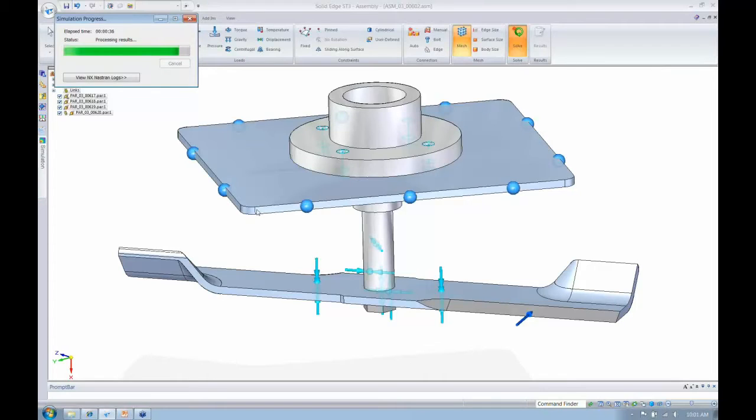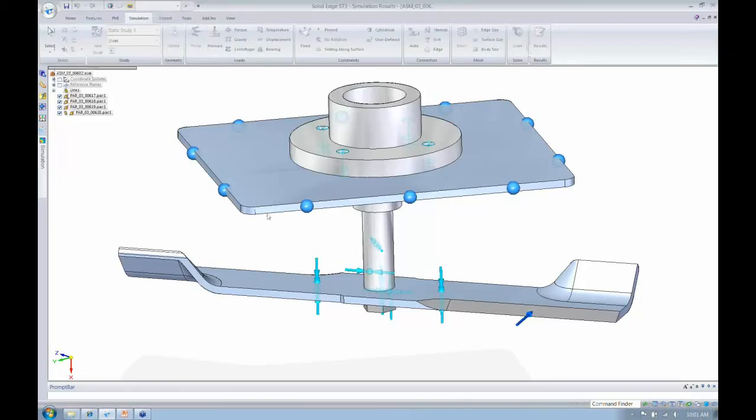So if I'm using plates or things that are very thin compared to their length and width, I'm going to want to use those surface elements because I just need one through the thickness because it captures the rotation, and also I can use a bigger element because it's represented by that 2D geometry, and I don't have to have all those tiny elements through the thickness there.